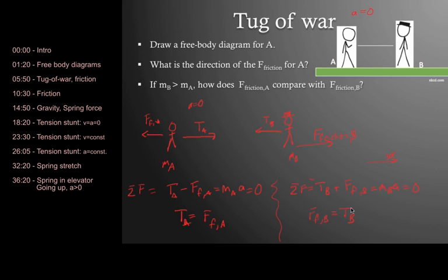So I have two equations and two unknowns, these two tensions. But one thing that you know is that the rope, pulling this way, we call that TA. And then TA is going this way, and then TB going this way. It is impossible for TA to be anything other than TB in magnitude, because the rope would have to be exerting some force inside of itself.